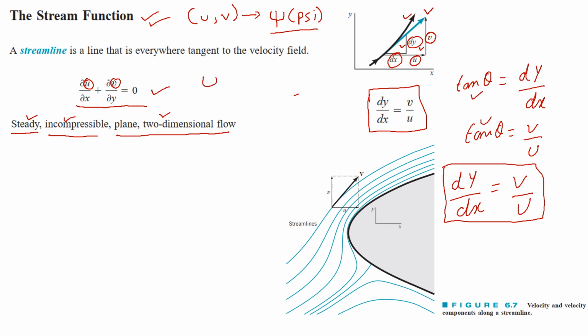That is, we can write this psi in terms of u and v, and we can also write these u and v velocity vectors in terms of psi. So you can see that by representing these two velocity vectors with a single term, we will get one unknown, that will be psi, for this single equation.